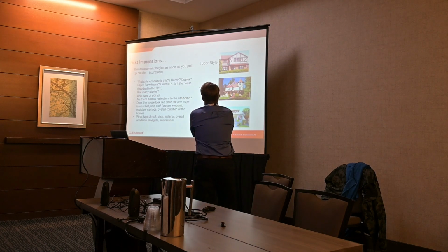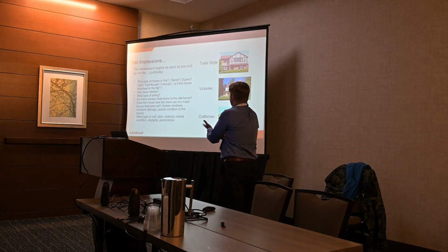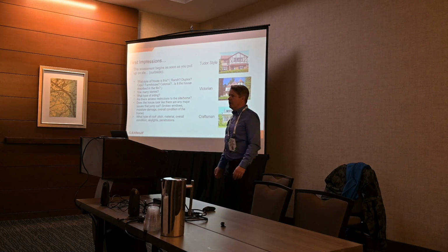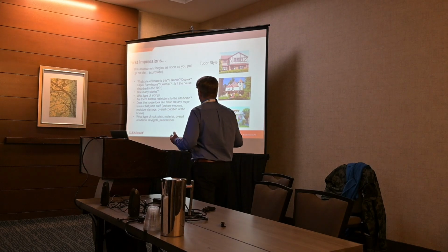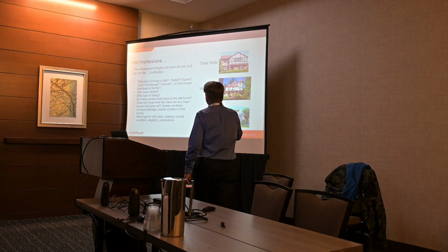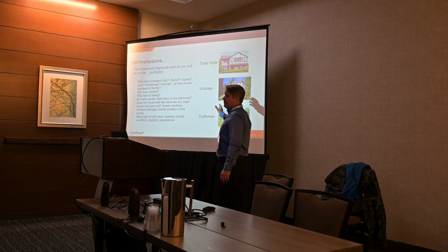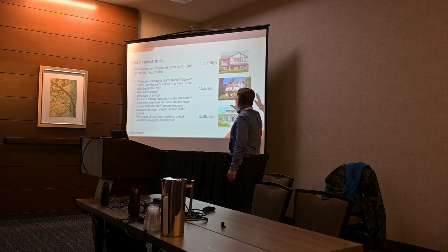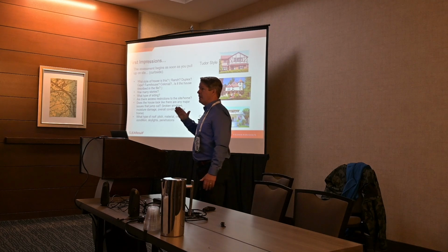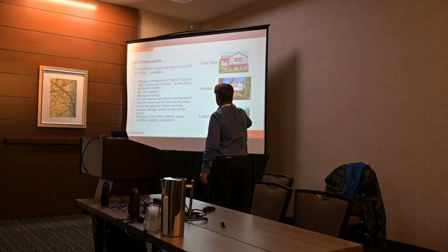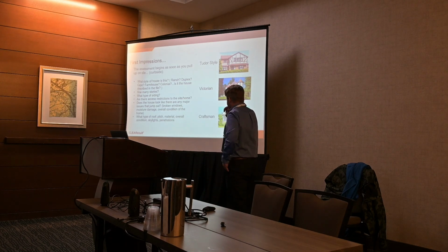Okay, so you pull up, and the assessment really begins the minute you pull up, right? So what style is the house? Is it my favorite house, which is the ranch, or the house that I hate the most, which is the Victorian, right? Is it the house that was described in the file? How many stories high is it? What type of siding? Site restrictions are a big thing, right? If we need to get a truck into the backyard or close to the house, is there anything stopping us from getting there? Real steep driveways, right? Getting a cube up a real steep driveway is tough. Or there's trees hanging over wires. So, are we going to have some type of problems with that?